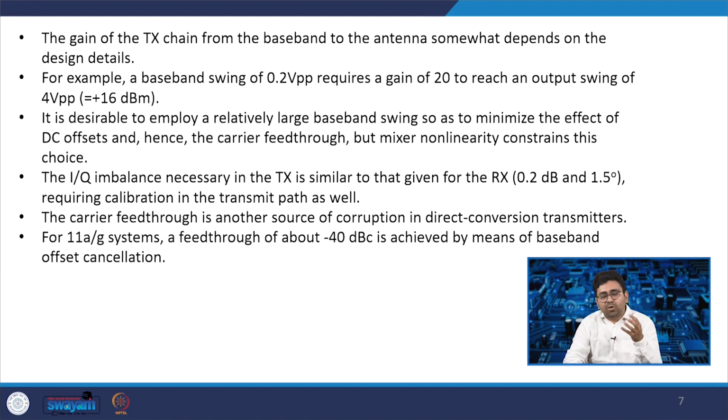So this is how, while designing the transmitter or receiver, you consider all these points. You first find out each parameter of the LNA, mixer, PLL frequency synthesizer, phase noise, VCO, frequency planning, then you can start designing the individual components, and then you can club them and make a complete transmitter and receiver chain.